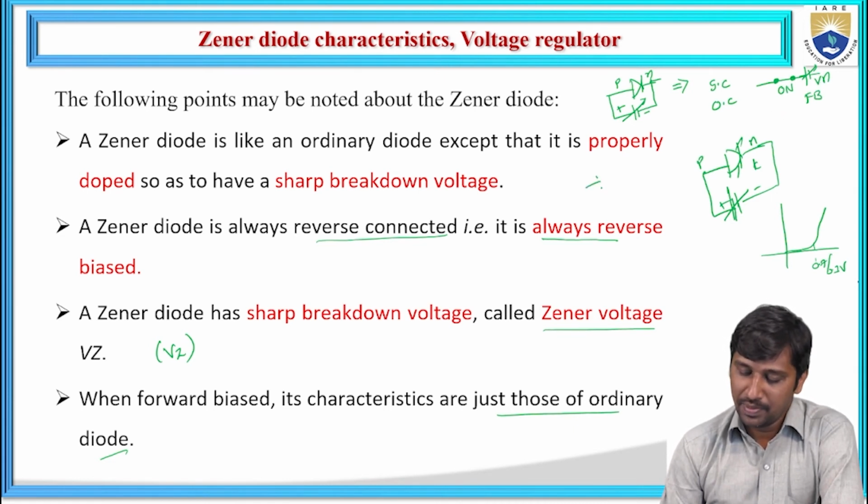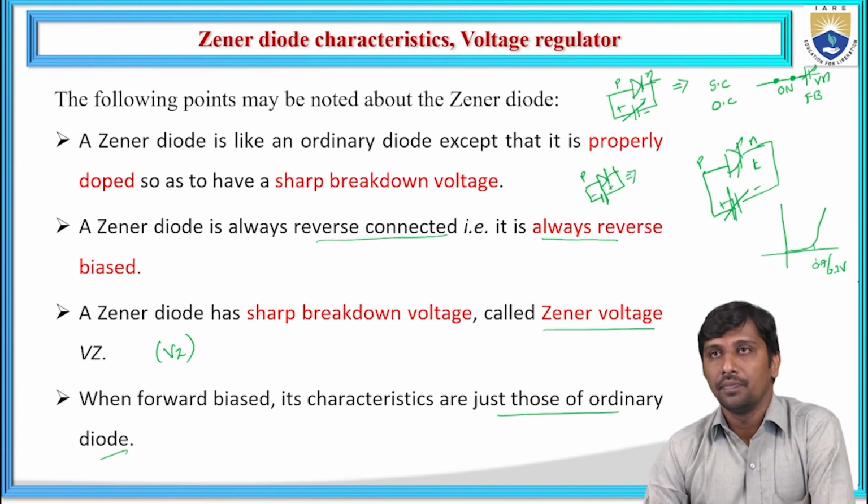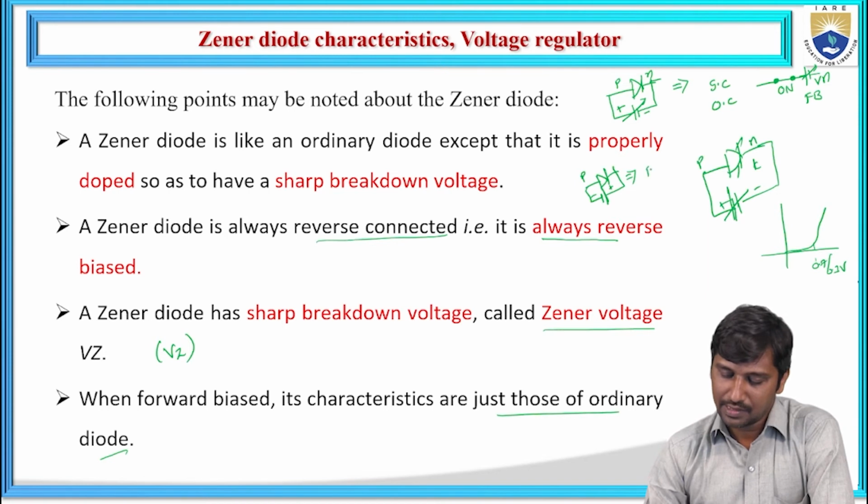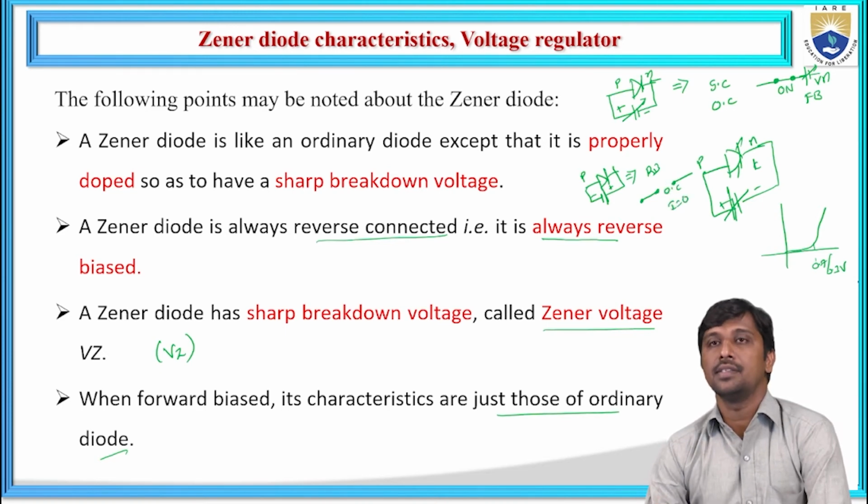Similarly, when a PN junction diode is reverse biased, meaning P is connected to the negative pole of the battery and N is connected to the positive pole, then the diode is replaced with an open circuit, hence the current flowing across this device is zero.